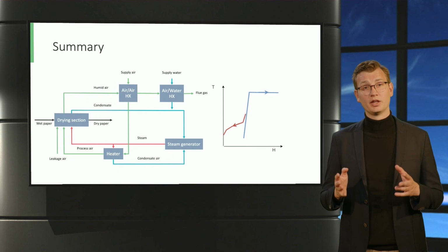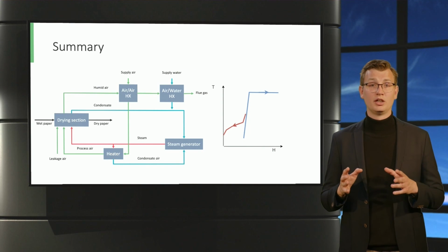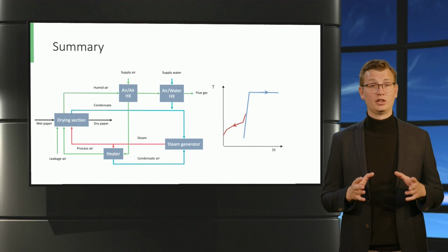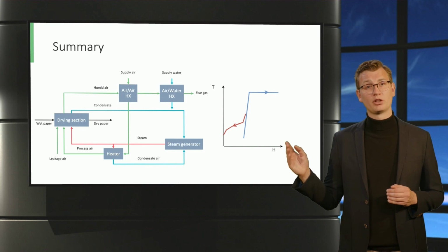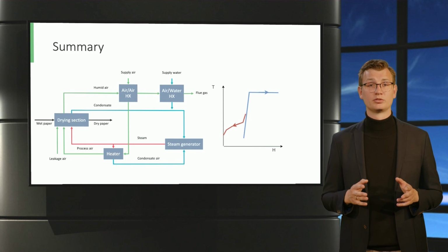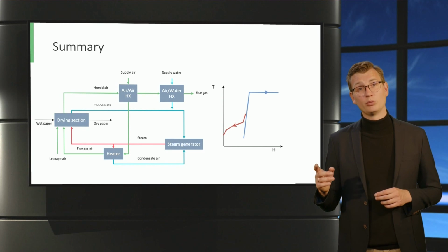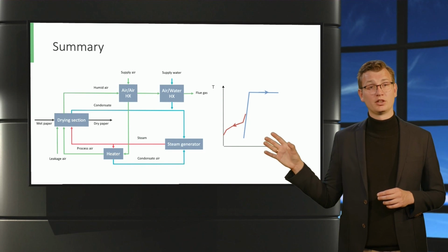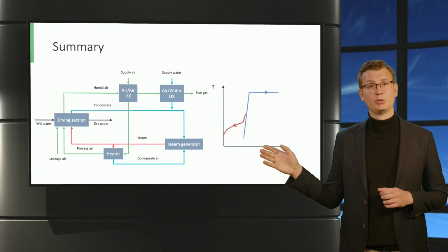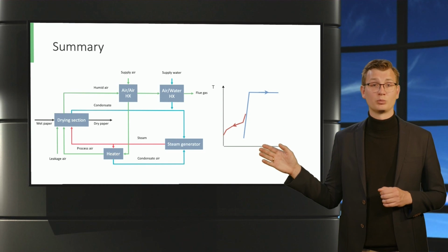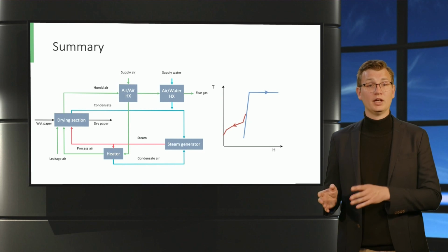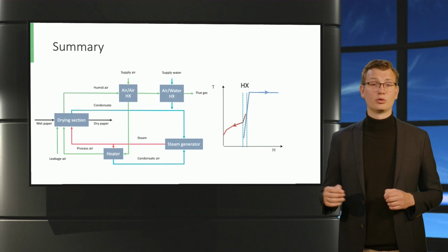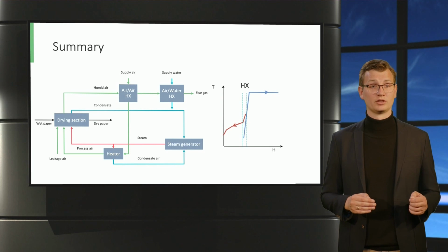In summary, in this video we discussed the energy efficiency options that use waste heat. If we apply our knowledge to the case study, we come to the following technology options. 1. If we look at the composite curve of our case study, we see that there is an overlap between the heat requirements to form steam out of water and the heat that is available in the humid air. Still, a lot of heat is required for the formation of steam after disintegration.